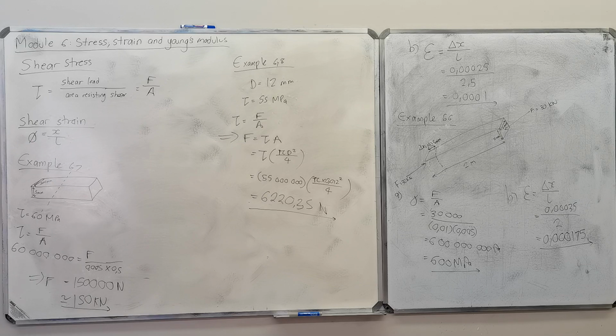Double shear, right? I'm on page 149. Double shear is obtained where a pin joint is supported at both ends, and this is called, I may not pronounce this correctly, a clevis and a clevis pin. A clevis is a U-shaped piece of metal at the end of a beam for attaching tackle, etc. If you look at figure 6.19, see that U-shaped thing? That is a clevis. They give you more of a schematic representation on 6.18. On 6.19 you see the actual thing.